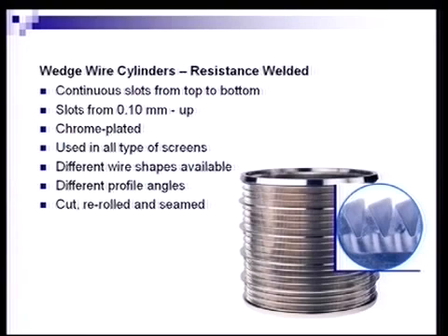Then they're cut off of the mandrel, flattened and re-rolled in an opposite direction. All those stresses are put on the basket, and all that stress ends up as a residual stress in the structure itself, so that under load these can be subject to failure. But it's a very, very good method by which we can get a higher open area for the same circumference and length of a screen basket.